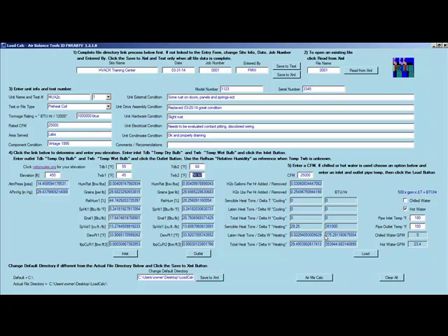hundreds. Okay, so the other thing we want to do is this is 25,000 CFM, and this is a hot water coil, so we would check the hot water coil. We have an entering of 180, outlet of 150, and here's the 500 times GPM times delta T is going to be our BTUs per hour. So let's go ahead and try and do that.